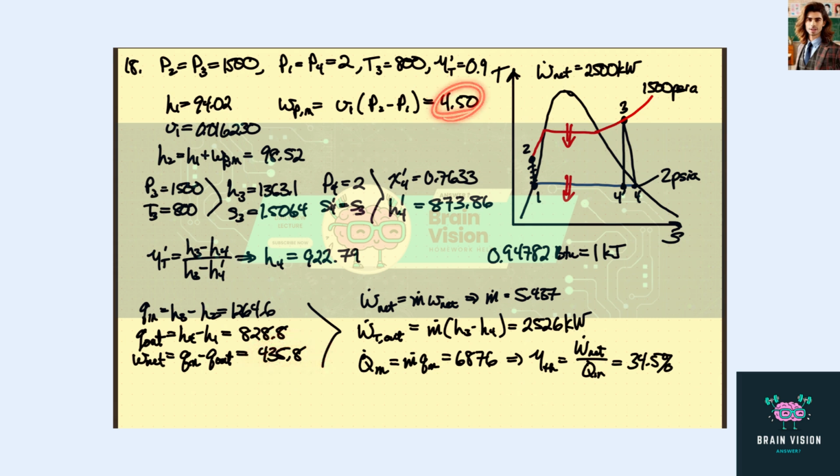You can see that this is like 1% of the net power that's out. So if we neglected this, we would just have roughly 440 BTU per pound mass. So we shouldn't get much of a difference, and we'll see that that is indeed the case.